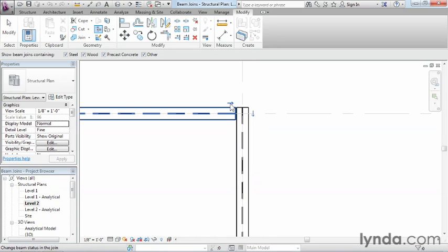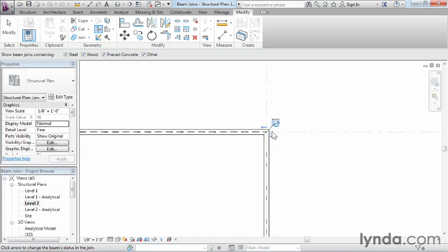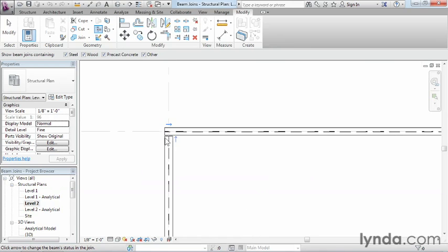Now, if I click on this arrow again, you notice how if they're sort of going apart from one another, pointing away from each other, it's allowing them to clean up and they're coming together at a 45-degree angle. And this is how I want these to clean up in this particular condition. So let's go ahead and take a look at that and try to do that here on the other end.